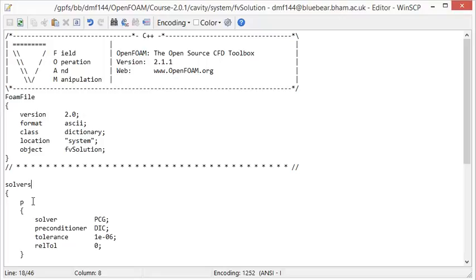of the field. After each solver iteration, the residual is re-evaluated. The solver stops if the residual falls below the solver tolerance, or the ratio of the current to initial residuals falls below the solver relative tolerance, relTol. The tolerance should represent the level at which the residual is small enough that the solution can be regarded as sufficiently accurate. The solver relative tolerance limits the relative improvement from initial to final solution. In transient simulations, it is usual to set the solver relative tolerance to 0, to force the solution to converge to the solver tolerance in each time step.